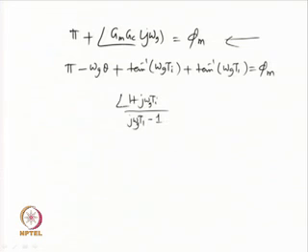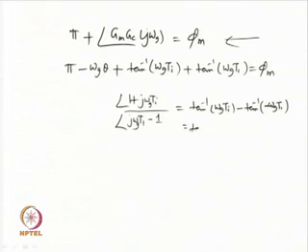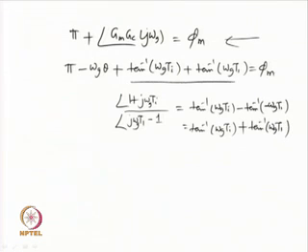So, the phase angle of this one and phase angle of this one can be written as tan inverse of omega g Ti minus tan inverse of minus omega g T1. This minus of minus will give you ultimately tan inverse omega g Ti plus tan inverse omega g T1. So, that is how I have obtained the phase angle from the loop gain.